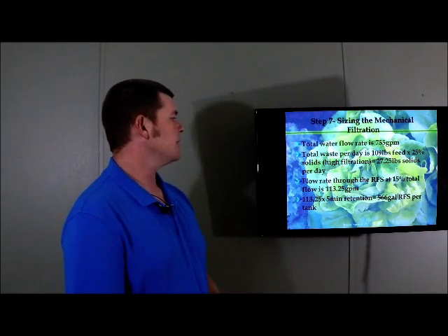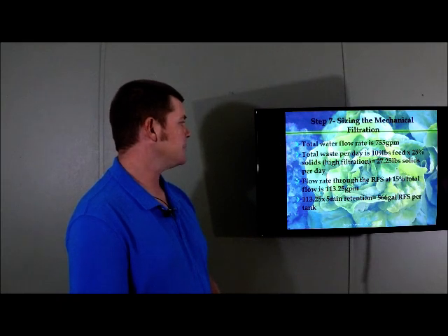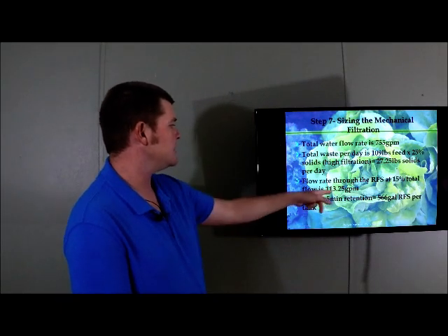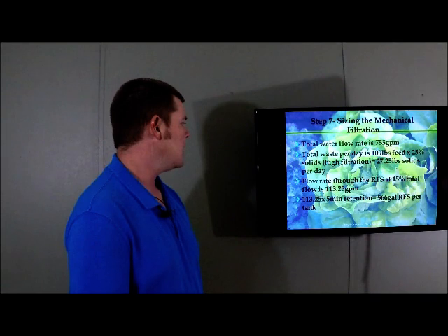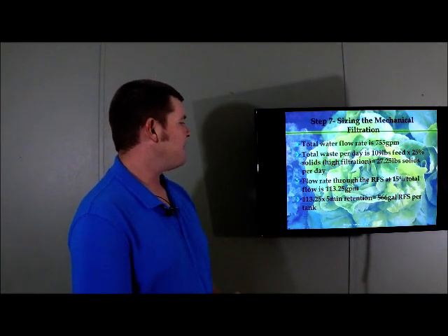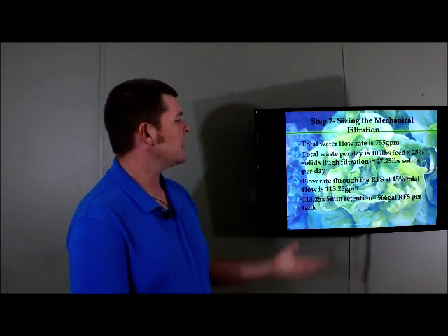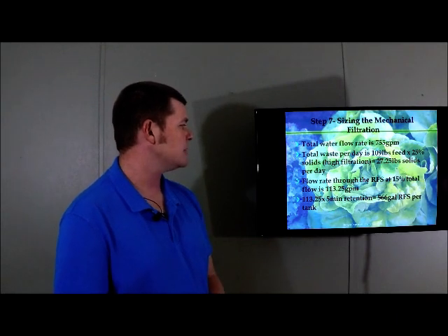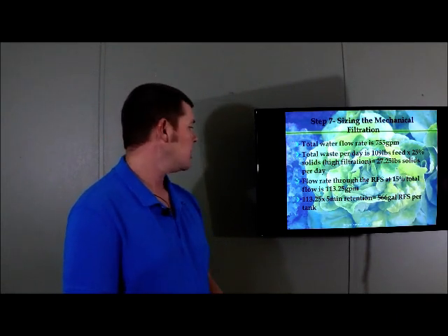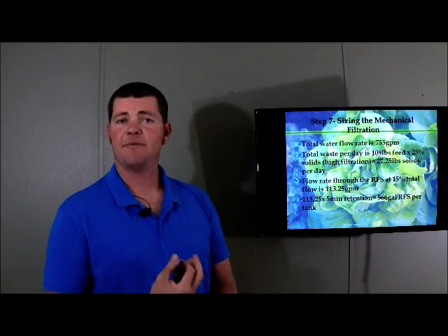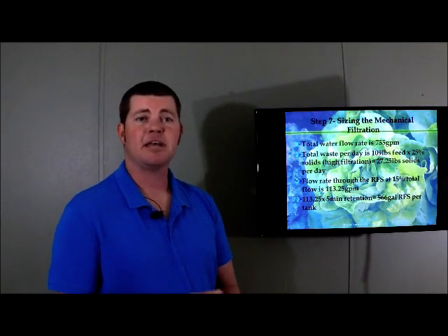Flow rate through the radial flow settler at 15% total flow is 113.25 gallons per minute. We multiply that by 5 for a 5-minute retention time, and we get 566 gallons for a radial flow settler, and that's per tank. Okay, so we'll have 4 radial flow settlers, 1 per tank.